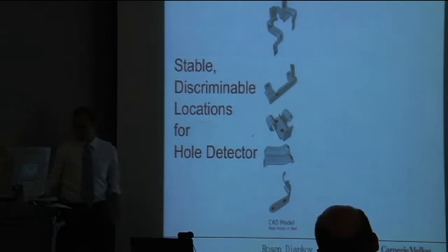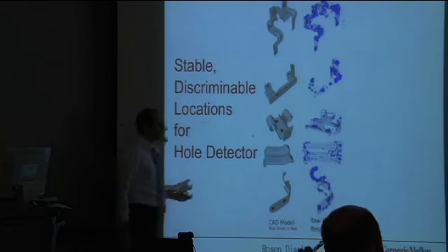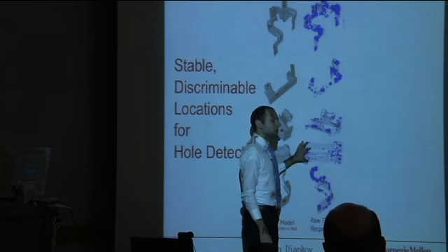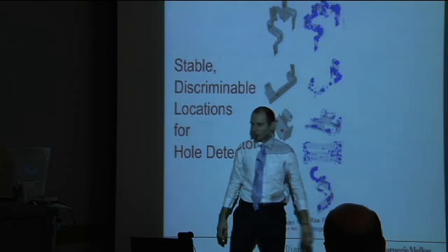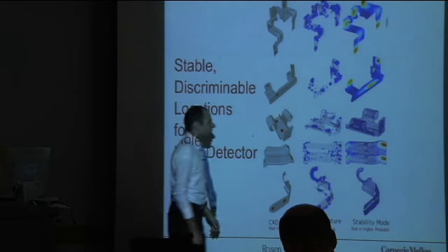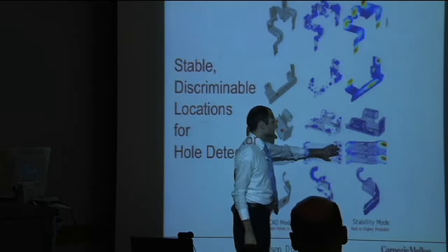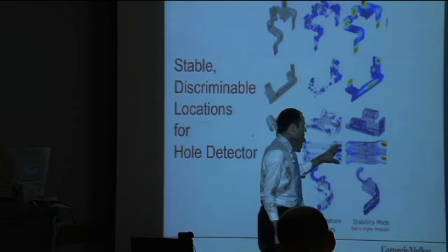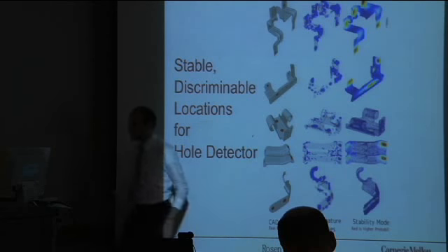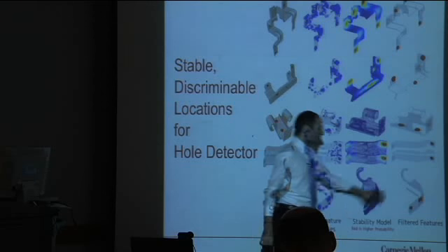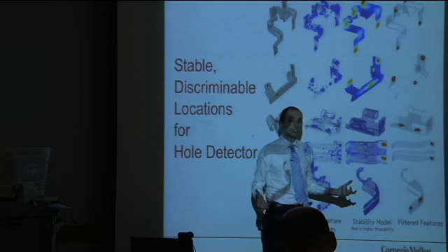So what this allows us to do is, for a particular CAD model, because we have this golden labeled data, we can actually, for a particular hole feature detector, map where all the hole features fire on the object surface. And then, doing some statistical analysis, this is a kernel density estimation of the density of each of the features. We can use this type of model to prune out bad features and really only leave the ones that are the most stable and fire the most statistically.